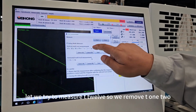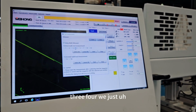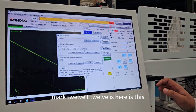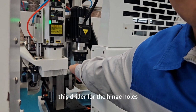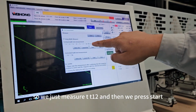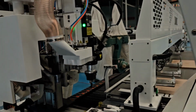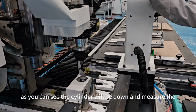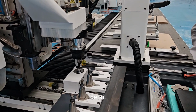Let's try to measure T12. So we remove T1, 2, 3, 4. We just mark 12. T12 is here. This is the driller for the hinge holes. So we just measure T12 and then we press start. As you can see, the cylinder will go down and measure T12.